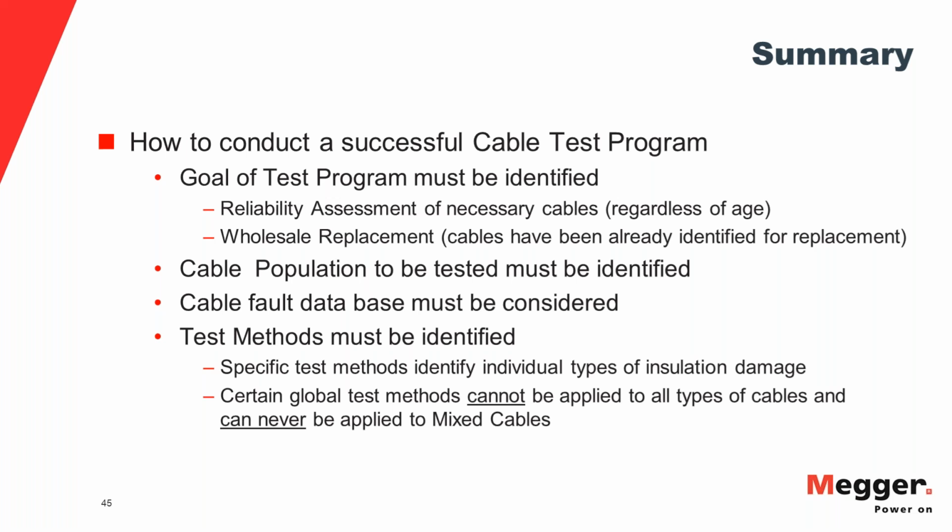You need to test it. That's the practical component. You should always consider, if you have a fault location database, so you have an understanding of whether this circuit already failed or this circuit is new. And always keep in mind, certain test methods are not always applicable for everything. Again, holistic concept, you need all three, VLF, 10 delta, and PD, because certain methods, specifically the global methods, one of them is the 10 delta, cannot be applied to certain types of cables and never really to mixed cables.